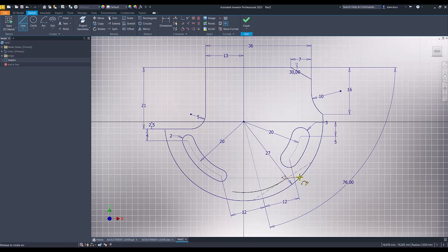I go to the circle. I draw another arc, same to the left. You keep press the left button and you go there. This arc has a continuity. I cannot disturb that continuity. I use split to create two cuts, and I make this segment as construction. Right click, construction.